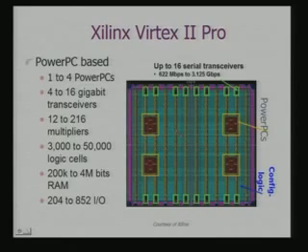This is an example of this kind of programmable platform that I was talking about, Xilinx Virtex-II Pro. It has got 4 PowerPC processor cores sitting on the same SoC along with the FPGA logic to add on the hardware, and it has got serial transceivers to transfer the data.